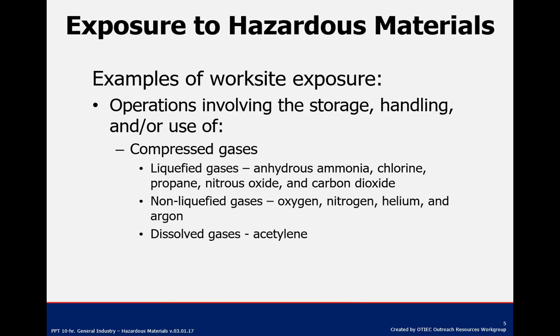OSHA standards 29 CFR 1910 subpart H lists requirements of the following situations, all of which have the potential to expose employees to hazardous materials: the proper use and storage of compressed gases, the proper use and storage of flammable liquids, spray finishing operations using flammable and combustible material, storage and handling of liquefied petroleum gases, the process safety management requirements of highly hazardous chemicals, the work associated with hazardous waste operations and emergency response, dipping and coating operations.